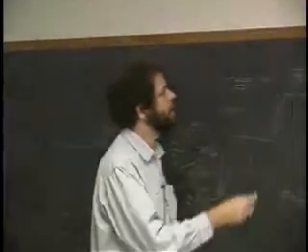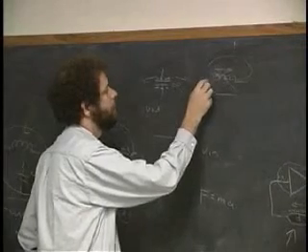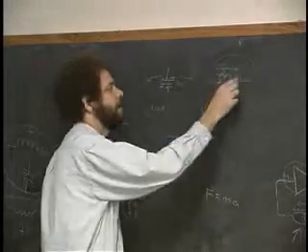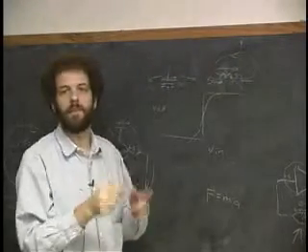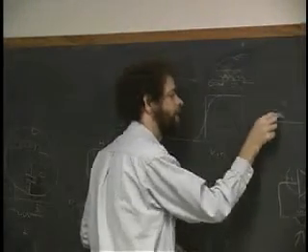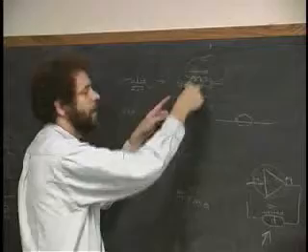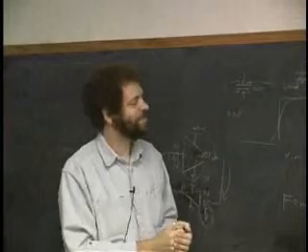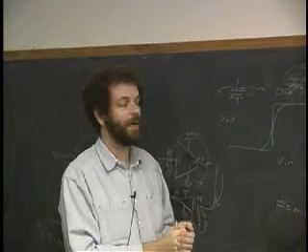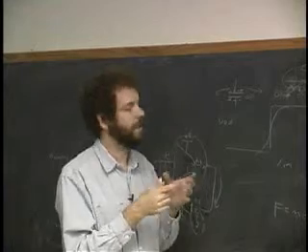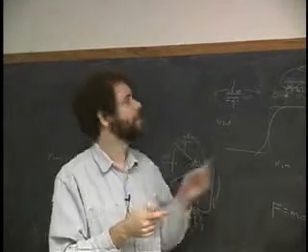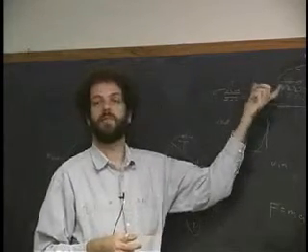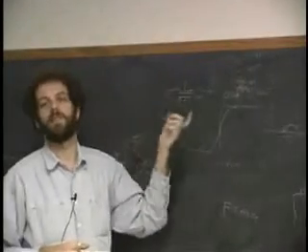The idea is kind of the same here too. The charge carriers are going in an overall direction around a coil like this. That creates a magnetic field around the thing. If you have a wire that goes like this, the field kind of goes around in a circle like that. And then if you coil it up, you get a bigger field, okay? I'm going to leave this all to Sam Jr. But as a result, the magnetic field itself doesn't want to change either. And so when you try to slow down the amount of current that goes in this thing, it actually develops a compensating voltage across the coil, which tries to keep the current going more.